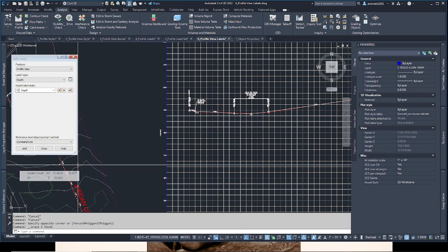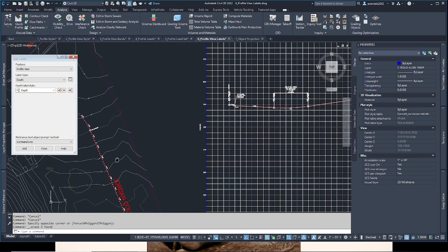surface here. Projecting blocks and points are a little different, but very similar. AutoCAD points, Civil 3D points, and blocks, AutoCAD blocks, blocks or drawings within drawings essentially. They're handled a little different than linear objects. They're represented with a marker, and they project away and they draw into the plan view. Okay, so they draw into this plan view here, but you do have the ability, the main thing is to assign elevations to those projections,